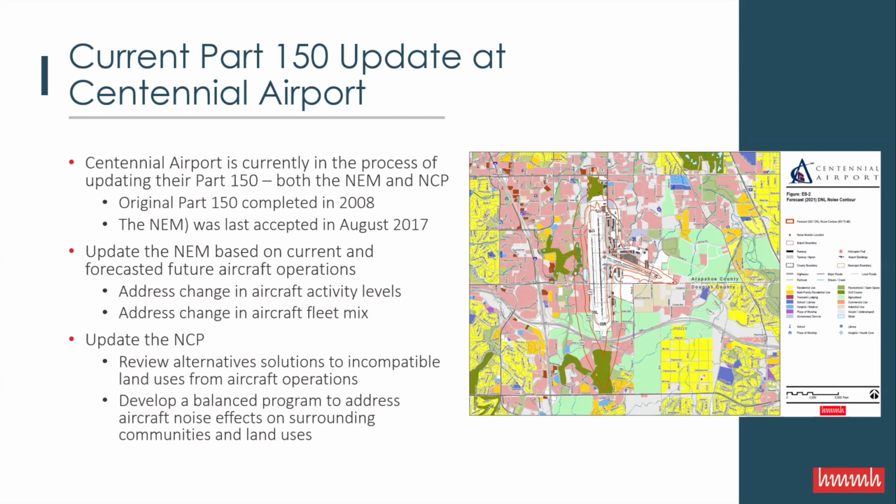The regulation says at least 5 years out from the existing condition, but it's become standard practice to be exactly 5 years out. Part of the reason for that is that the FAA forecast of funding is out at 5 years at a time, so they can't look much past 5 years for funding. So they've recommended airports stick to an existing condition and a 5-year forecast condition.